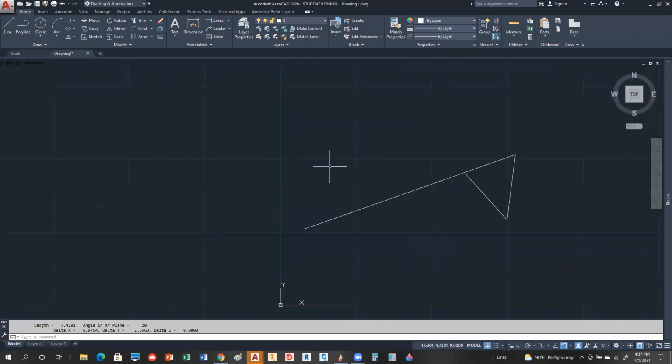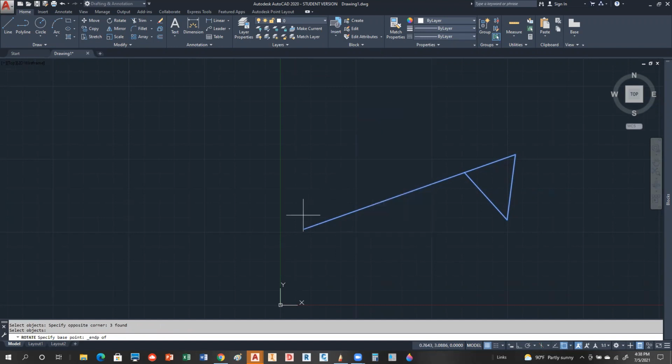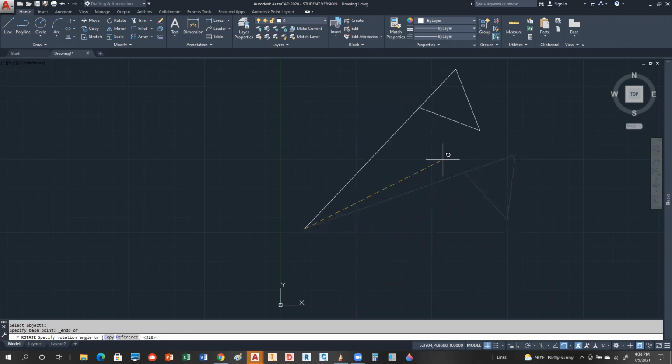So when I do this, what I'm going to do is have AutoCAD measure the angle on this to 14 sig figs and then tell it that I want it to be 90 degrees using a reference option. Okay, so this is a little tricky. Let's go through it. I'm going to do the rotate, again, just like normal. I'm going to select my objects to rotate. When I'm done selecting my objects, I just hit enter. I'm going to select the base point. I'm going to go ahead and put my base point here. And notice I'm in that normal mode where I'm just specifying a rotation angle.